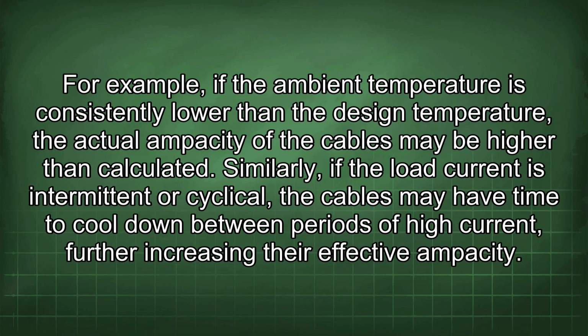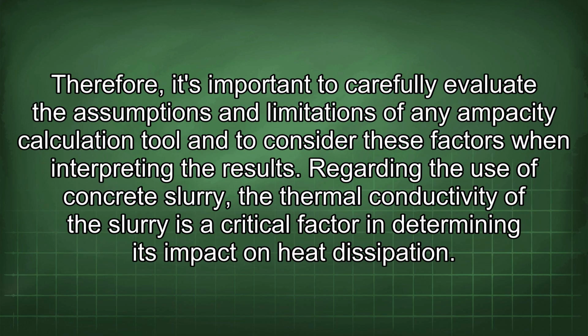For example, if the ambient temperature is consistently lower than the design temperature, the actual ampacity of the cables may be higher than calculated. Similarly, if the load current is intermittent or cyclical, the cables may have time to cool down between periods of high current, further increasing their effective ampacity. Therefore, it's important to carefully evaluate the assumptions and limitations of any ampacity calculation tool and to consider these factors when interpreting the results.